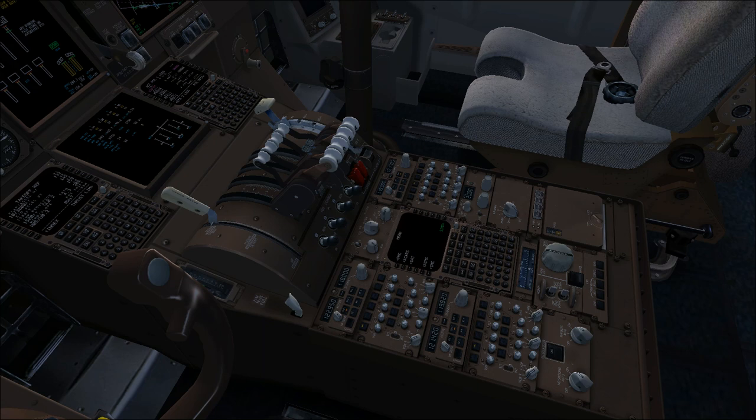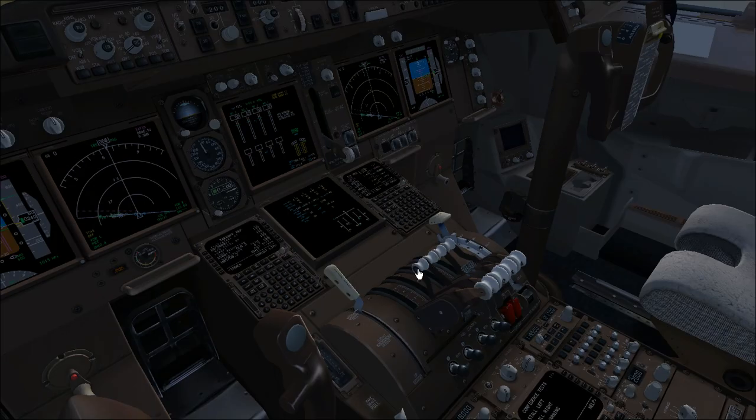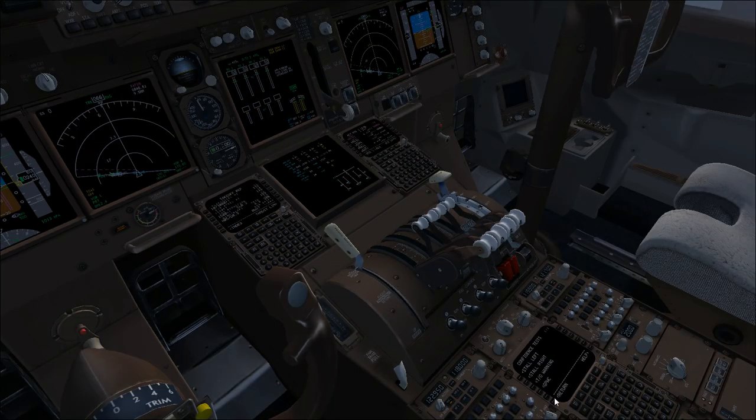Before start checklist is the next one. Before going for the before start checklist, I will show you the confidence test you can do here. Confidence test, CMC confidence test. You have the stall left, stall right, takeoff warning, and GPWC. That is the ground proximity warning computer, it's right. It's not GPWS. It's normal.